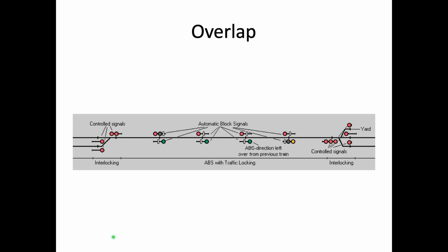With approach lighting installed, the signals stay dark until the train enters the block immediately in advance before the signals light up. In reality, it was up to the individual railroad's engineering department. Some liked this feature, and some didn't. The New York Central loved it, and I think that was because their automatic train stop system, the magnetic trackside ramps, used a lot of current. Pennsy didn't.